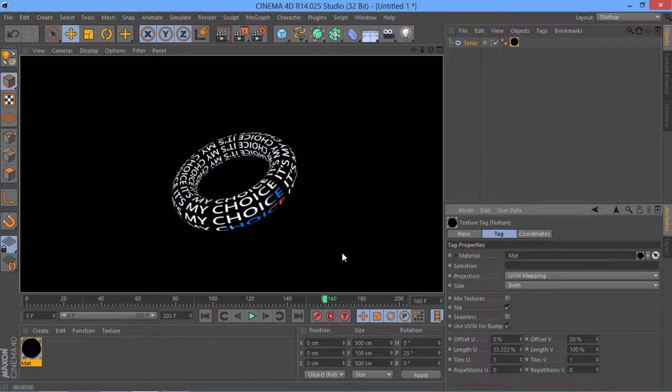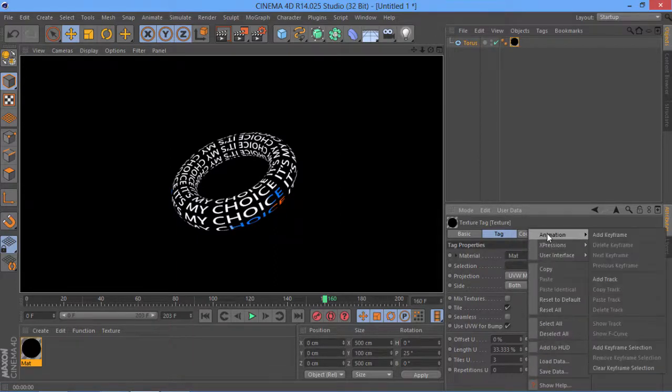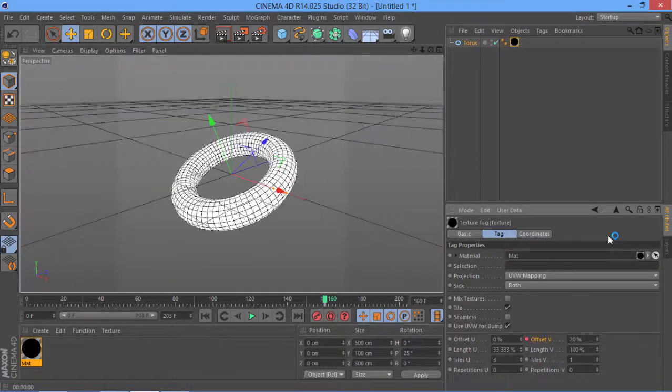Now, time to animate it. Just right click on offset parameter and add a keyframe here. Now, since we have kept time lag of 15 frames in between each animation layer, we will have to add next keyframe after 15 frames, that is on 175 frame. And here let's decrease offset value by 10% because we have 10 copies in texture tile composition in After Effects.